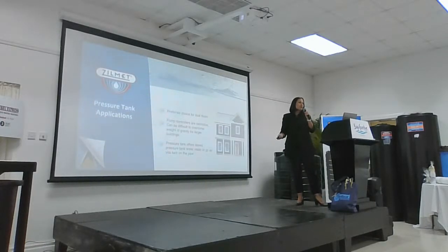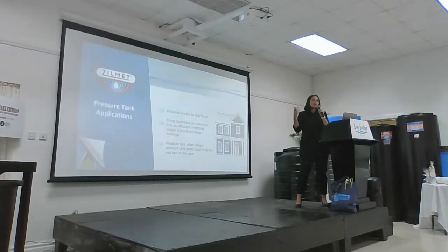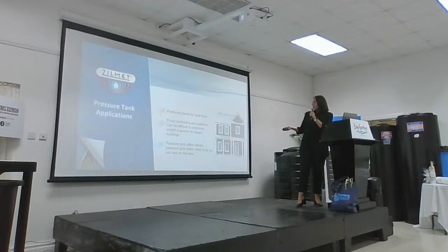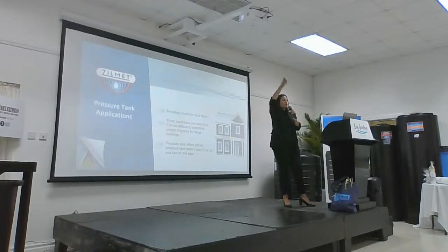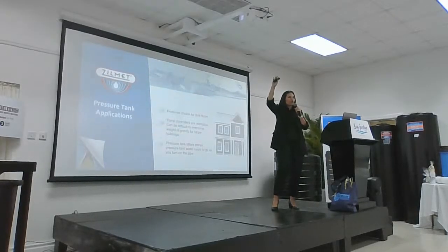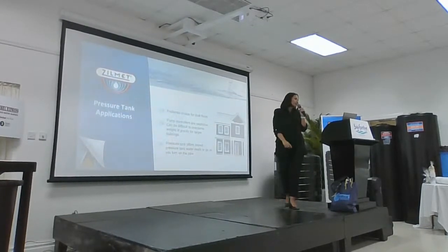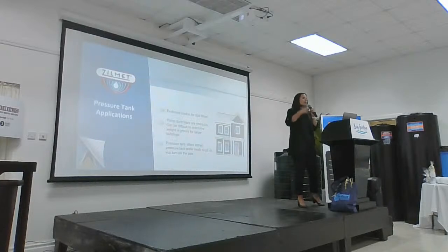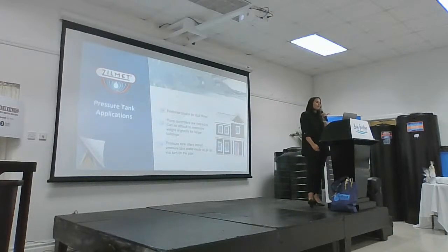So where do you install the pressure tank? Well, pressure tanks are a preferred choice for larger applications. Pump controllers can be restricted by nature, and it can be difficult for them to overcome the weight of the gravity of water in the pipes. So we always recommend pressure tank applications for double and triple story homes and offices and commercial applications. The pressure tank also stores water pressurized. So it is again less work on your pump. And the benefit for that is that it also gets to run for longer periods of time, extending the longevity of your pump.